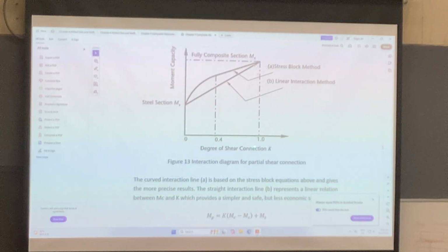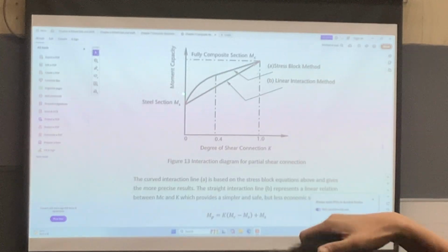connections，即係話，我呢度擺咗幾多嘅 shear studs 落去。The vertical one is the moment capacity. So you can see that you have the x-axis and then you have the y-axis. When I don't have any shear studs, what is the moment capacity? 如果冇 shear studs 嘅話，你屈呢個 composite beam，你屈到啲咩？成日屈到條 steel beam 咯，你石屎冇幫手嘛。So if I have no shear studs, the moment capacity will be just the steel section.